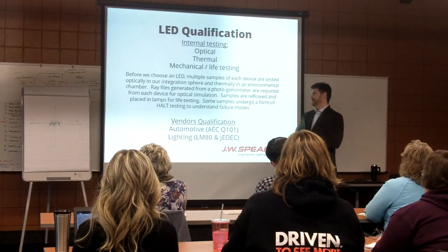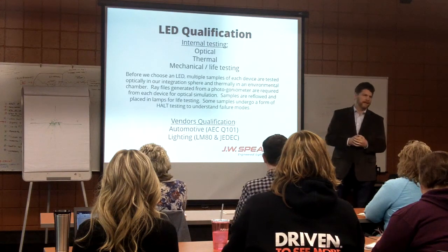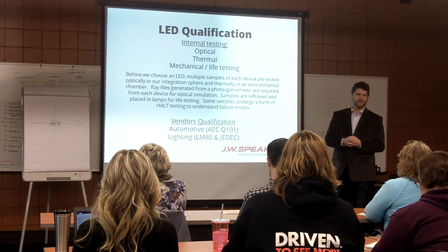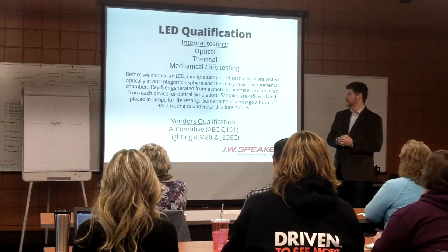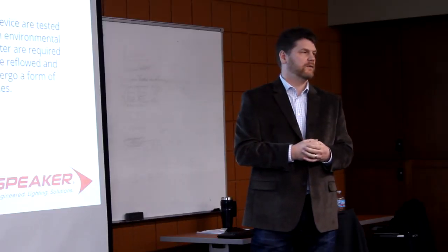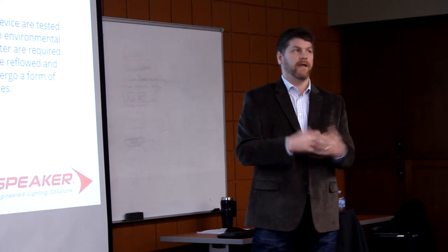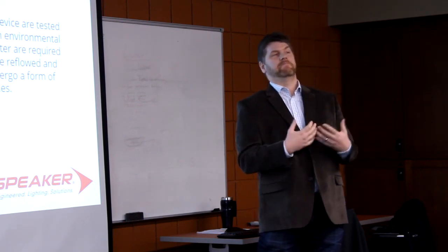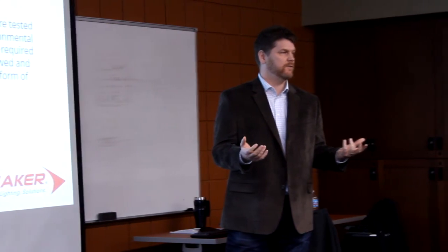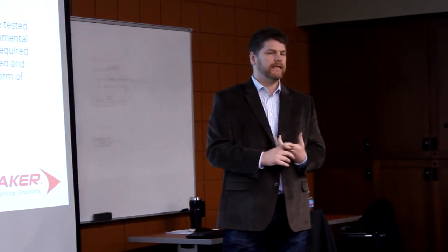In addition to that, sometimes we'll do HALT testing occasionally on some LEDs just to understand the failure mode. LEDs are very hard to kill, though. I want to be clear about that. Typically, the thing in our lamps that's going to die is very rarely the LED itself. The only thing that really kills LEDs is a ton of heat, and I mean a ton.